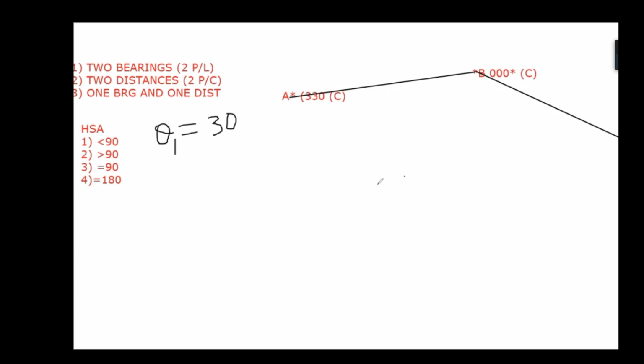If the angle between the two lighthouses from your vessel is 30, it is not a relative angle, it is the actual angle. Because if you have an error, suppose 2° east is the compass error, then your 330 compass bearing means your true will be 328.